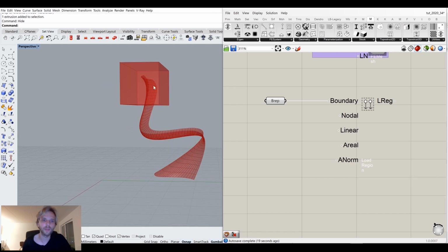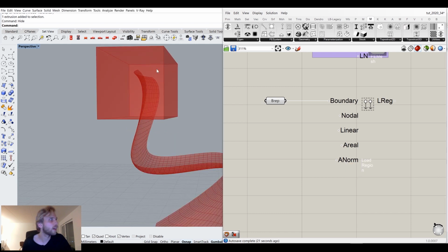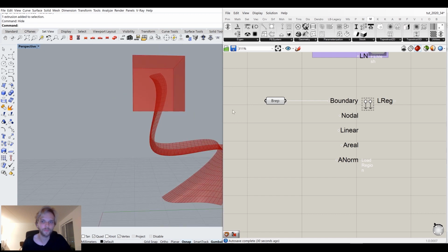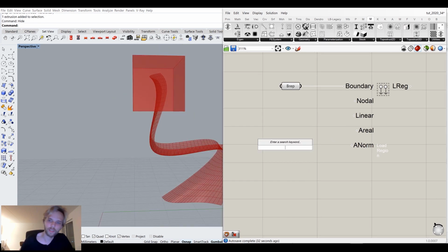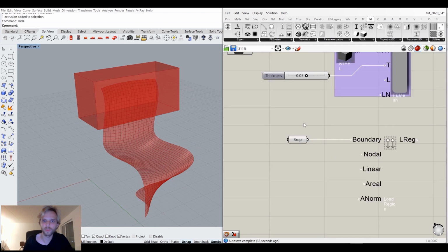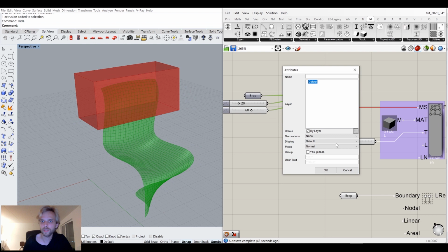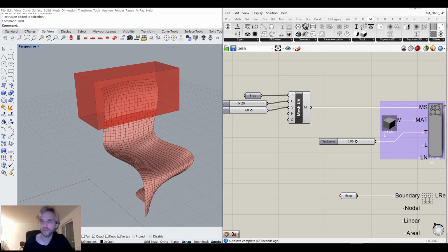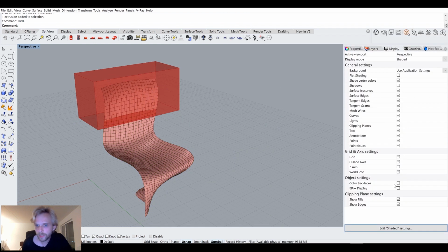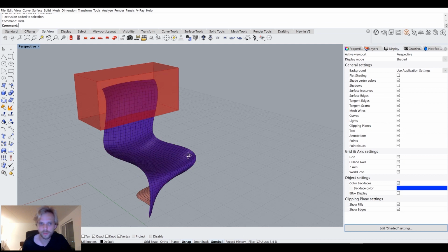So basically, it doesn't apply load straight down, but rather it applies it in a normal direction of the chair, right? So backwards. So let's do that. And here I will just specify, how do we do that? Well, first of all, I want to see the normals of it. So let me bake out the mesh just like that. And I will go to display. I'll choose color back faces to be turned on.